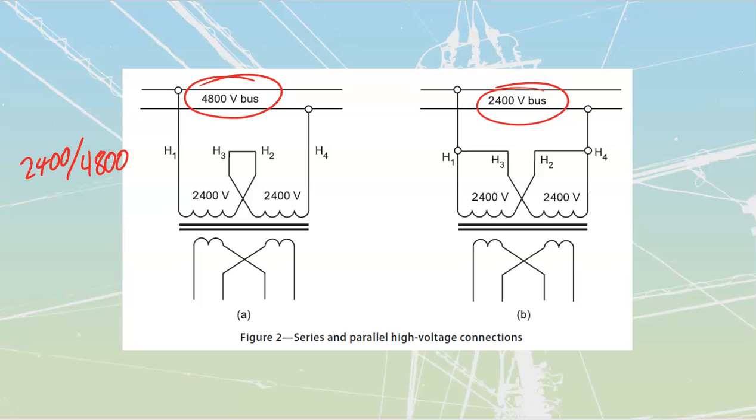We're going to start with a 2400, by the way. That would mean that each of my individual windings would have to be placed across from line to line. What they're doing inside of here is they're making what we refer to as a parallel connection. If I take a look at this winding here, I see H1 connects through all the way to H2. And H2 ties onto that line, jumps up to H4 over there. It's one way of drawing it.